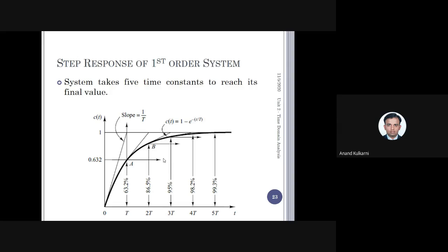For expansion stroke, the temperature is very high because the firing has already taken place. In compression stroke also the temperature is very high because you are compressing the gas. Whereas in the exhaust stroke and inlet stroke, the temperature is very low. So if you measure the temperature inside the IC engine cylinder, it is rapidly changing. And if you use a thermometer for that, you will not get any reading at all.